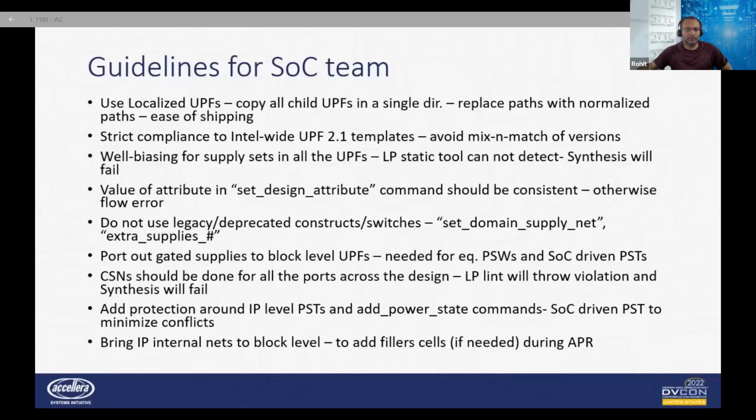We should do connect supply nets for all the ports and nets. Any missing CSN will result in failures in backend tools and violations in the LP static check tool. And all the internal supply nets should be brought to the partition level, because if you want to add fillers during APR on those nets, we will not be able to do it if we don't bring them out to the partition level.